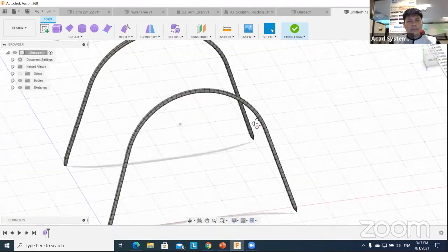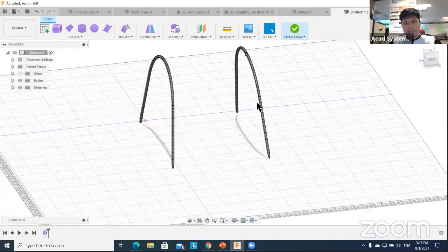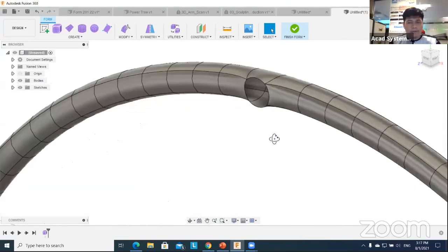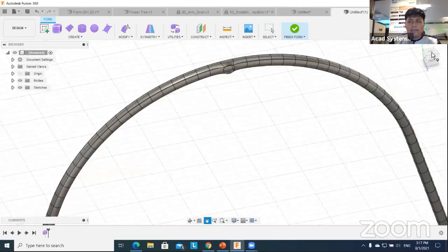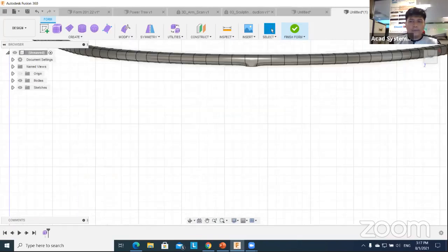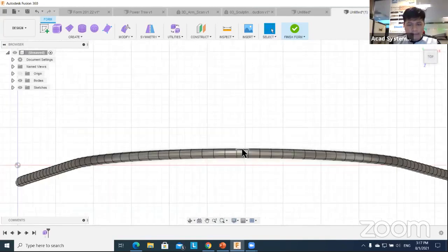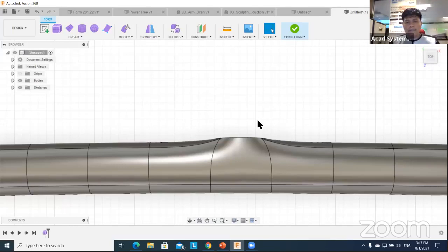To make a bridge between these two, you need to delete one area, then Freeform automatically creates the hole here. Make sure you choose a proper segment here also, the same shape as here.